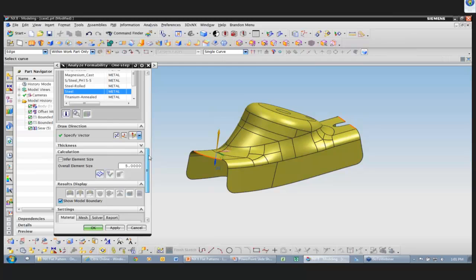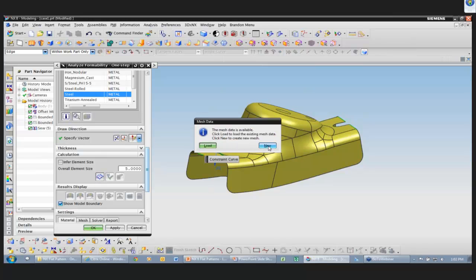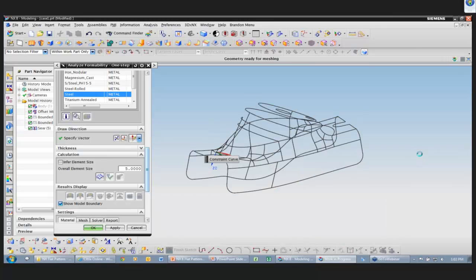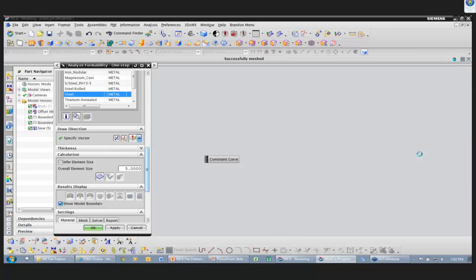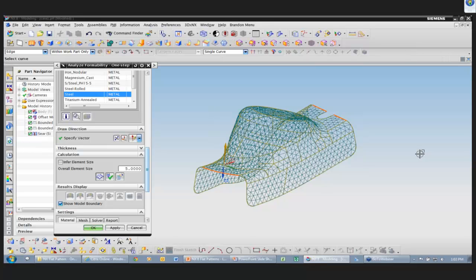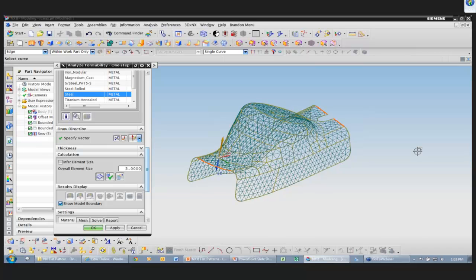And what we're going to do, because this is an analysis tool, based on those parameters, we're going to go out and create a mesh. If you guys have done any FEA or finite element modeling, you know that you're going to create maybe a solid mesh, or in this case, a surface mesh about that part. It's going to take those little triangles of the mesh and determine how to flatten those by holding those in boundary conditions, right?